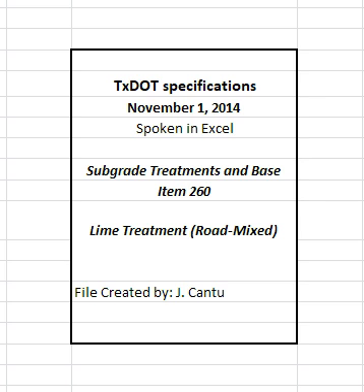When treating subgrade, bring the moisture content above the optimum moisture content to ensure adequate chemical reaction of the lime and subgrade materials. Allow the mixture to mellow for 1 to 4 days, as directed. When pebble-grade quicklime is used, allow the mixture to mellow for 2 to 4 days, as directed. Sprinkle the treated materials during the mixing and mellowing operation, as directed, to achieve adequate hydration and proper moisture content.